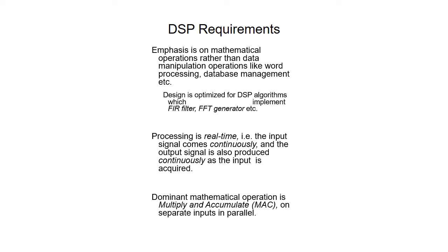Next will be the DSP requirements. The emphasis is on mathematical operations rather than data manipulation operations like word processing, database management, etc. The design is optimized for DSP algorithms, which implement the FIR filter, FFT generator, etc. The processing is real time, that is, the input signals come continuously, and the output signal is also produced continuously as the input is acquired.